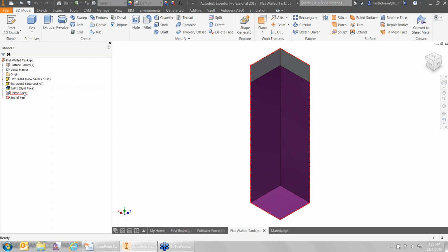Now that step isn't required by any means, right? You can take very, very simple geometry and use it within this space. Beyond that, I could have potentially thickened this to the actual wall thickness, but in this scenario, it's a very thin-walled component, and trying to use solid elements, a tetrahedral shape, to solve this might be very, very difficult. It would also take a long time to solve, because in order to get a mesh refined down that small, there would be tens of thousands or even millions of elements to make up this geometry. Instead, I can use a shell element to accomplish that same task.